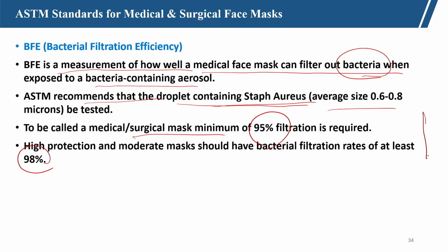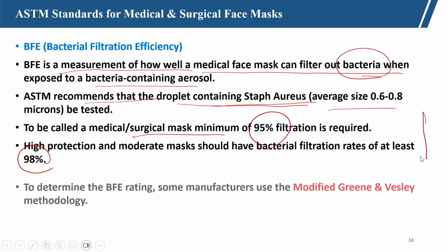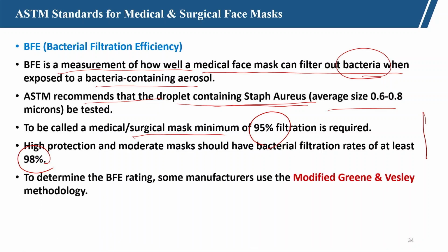So, to call it a medical or surgical mask, it should pass this BFE test. To determine the BFE rating, some manufacturers use the modified Greene and Vesley method.